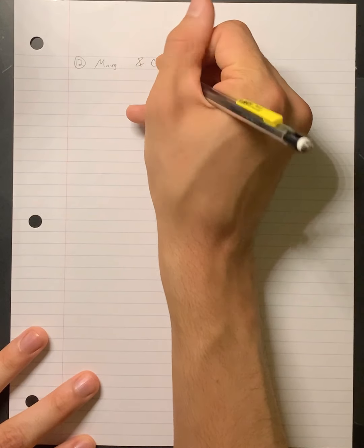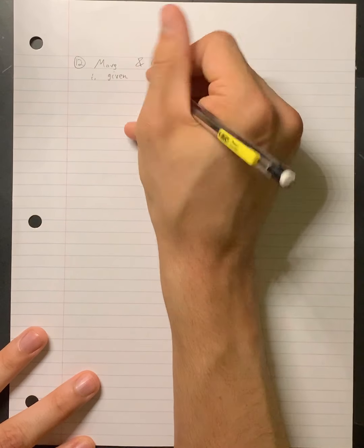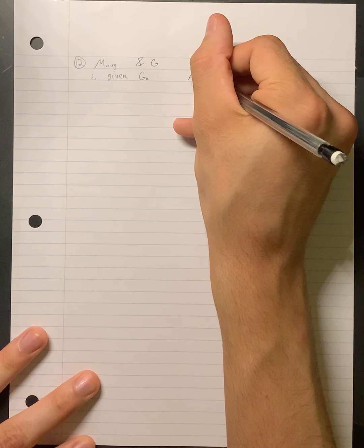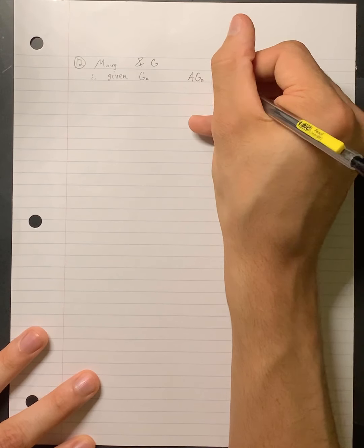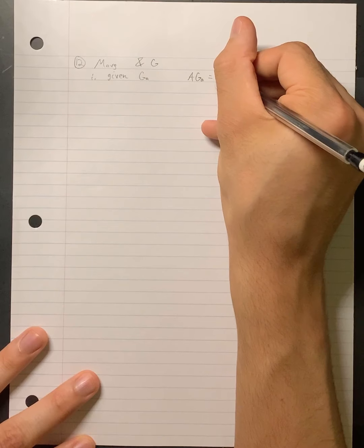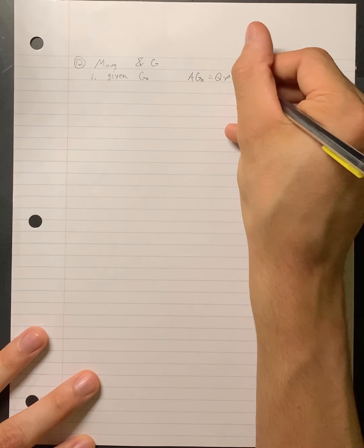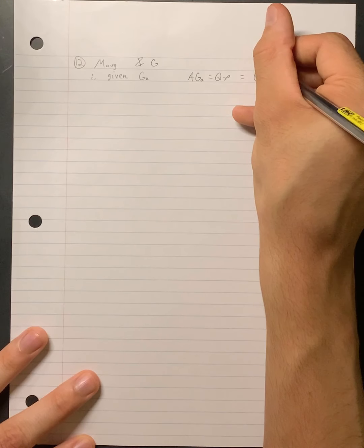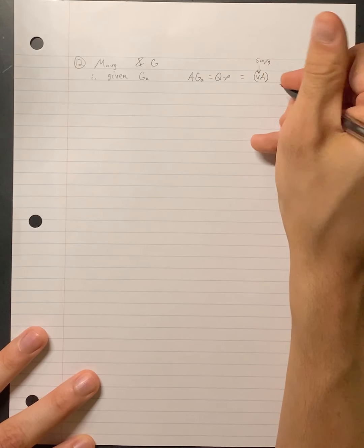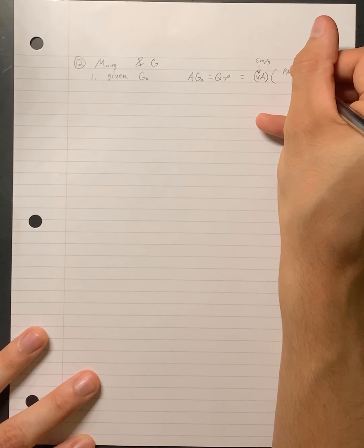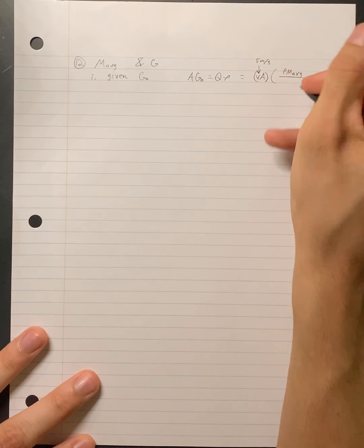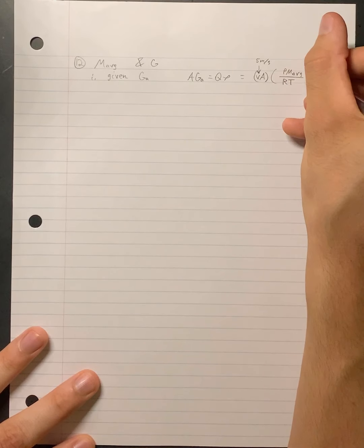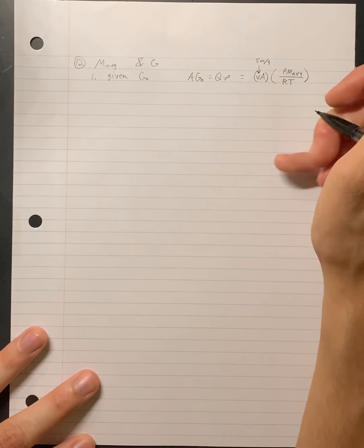First, we're given our mass flow rate of air. Area times the mass flow rate of air equals the volumetric flow rate times its density, which equals the area times velocity, which is that 5 meters per second, times pressure, then the M average, or average molecular weight, over RT. Now this gives us M average.